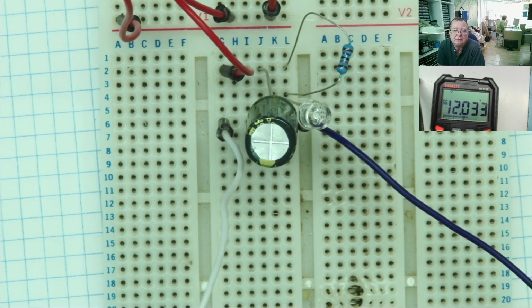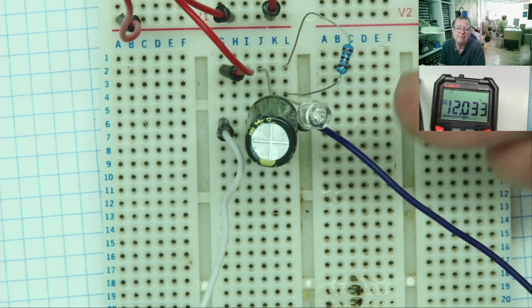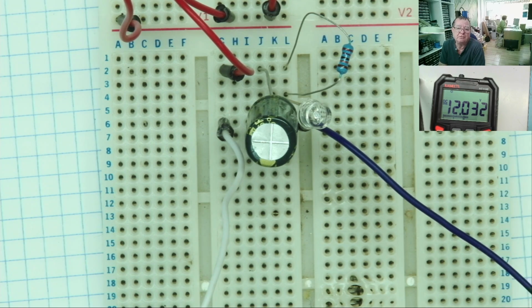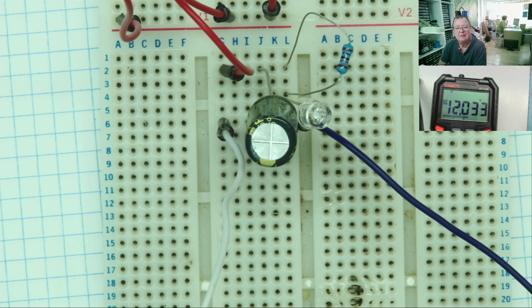But I think the first thing you'll notice is that the LED isn't lit. Why isn't the LED lit up? Well, this resistor is such a high value that it can't supply enough current to the LED for it to light. The LED can't light because it doesn't have enough current flowing through it. The higher the value of the resistance, the lower the current. Remember the early lessons we did, Ohm's law? Well, there's some more proof this is true, yeah? So, let's see what happens now if we take the power off. And the capacitor is discharging, it's just taking time. And the reason it's taking time is there is some current flowing through here, but very, very little.